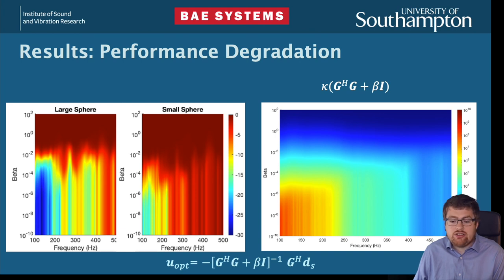Therefore, the value of regularization is clearly key to the system. If we over-regularize, we get a very robust performance across all the perturbations, but a poor performance in each case. If we under-regularize, we do well in the nominal case, but poorly in the perturbed cases. To view this in more detail, we can look at the broadband attenuation performance across the controller for each value